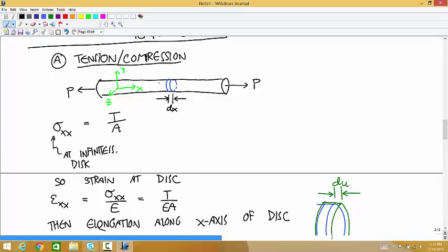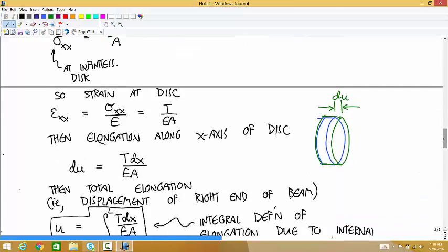But since we're assuming that the beam is much longer than these excluded regions, these bad deformations that we calculate at the ends are going to be swamped by the good deformations in the middle. And so even though we're adding in two regions where results aren't good, overall our results are going to be good anyways. Sort of understand what I mean? So what about St. Venant's principle and not trusting the ends? That's kind of the answer.